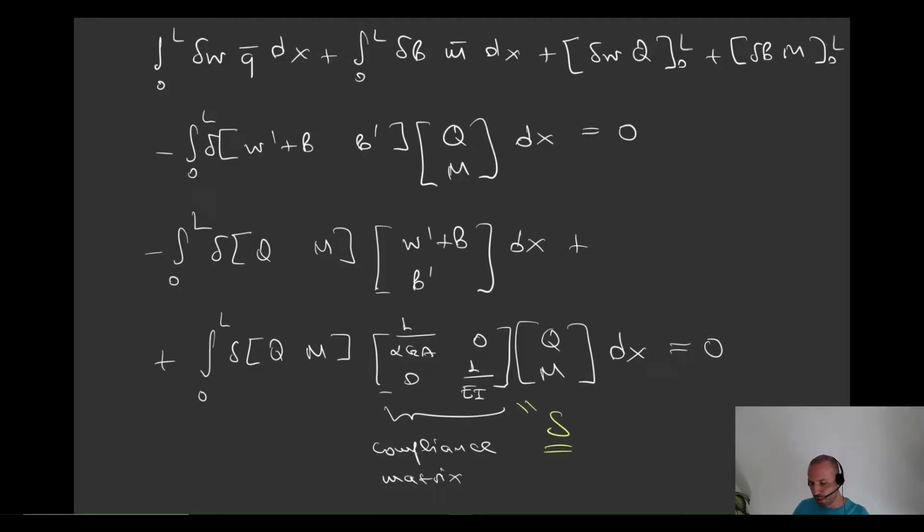So I won't expand on this because we already saw how to apply those. I mean, the first part is computed in the same manner as the internal work. We just use Gauss points and we multiply it with the corresponding externally applied distributed moments and vertical forces. Whereas for the second part, we can either apply the conditions strongly, meaning that we remove rows and columns, or we can use the methods that we've seen in the first part of the chapter, meaning the penalty or the Lagrange multipliers method. And of course, with respect to the boundary loads, we know already how to apply them. We have to go to the corresponding entry of the load vector and just add a value, whether that's a moment or a vertical force, so to put it in the right place.